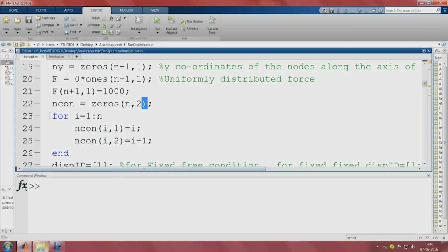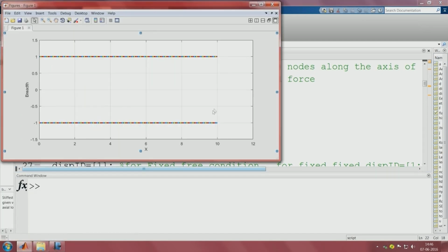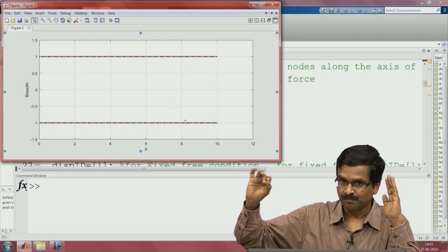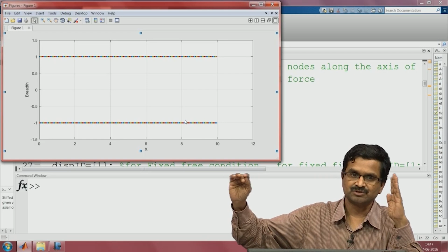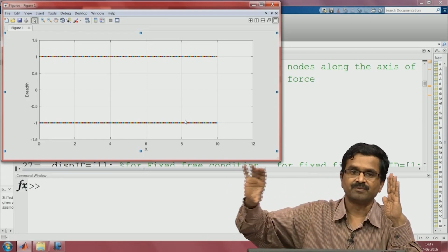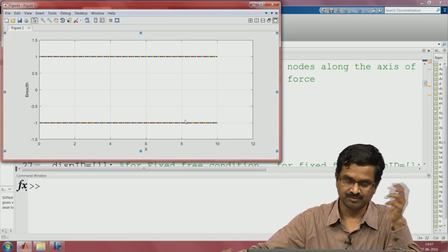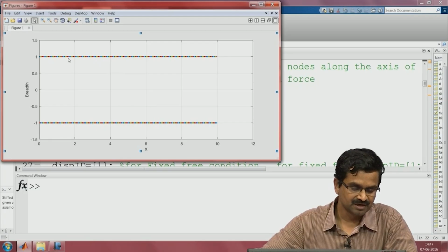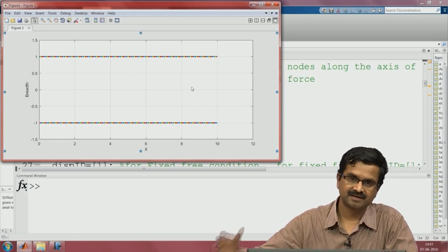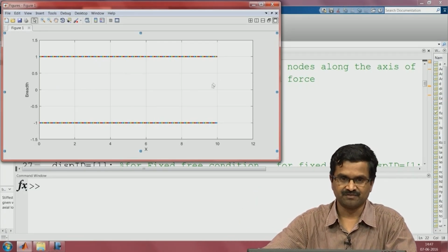Again it is running, it finished, we got a solution like this. So, here it is uniform cross section. That actually makes sense. If you want to make the stiffest structure for a fixed-free bar with a point load at the right end, the best solution is simply uniform cross section. That is what we got with the volume that we have. Now, the volume is 2 times the length times the depth that we have specified for the cross section.